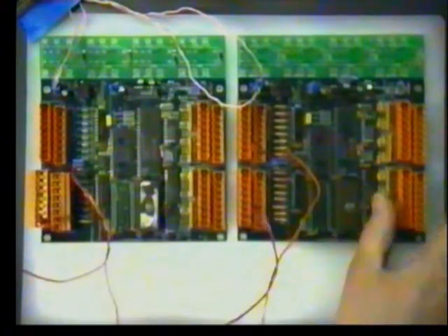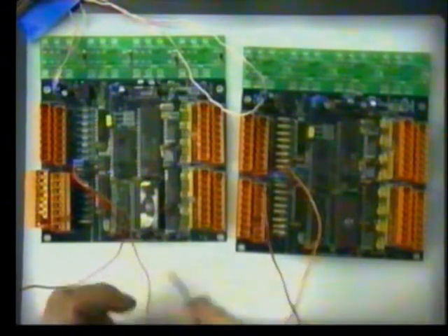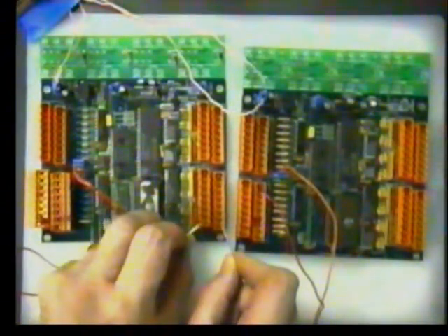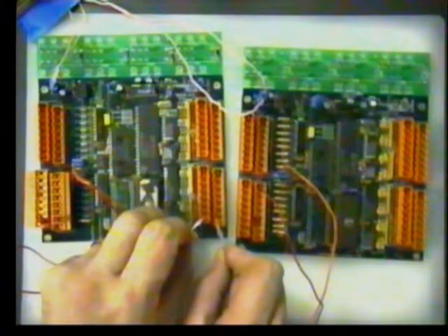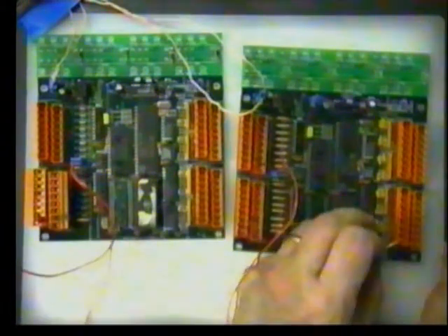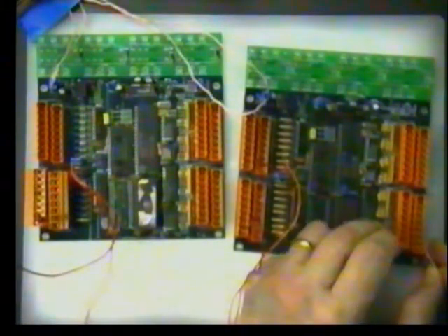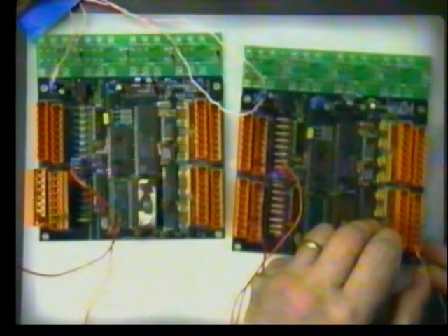So over the CAN bus network, which is just the two-wire connection, we are able to transfer real data between hardwired switches. There's the switches on one card being broadcast on the channel, turning on the actuators. These could be motors, drills, machines, whatever it is at the other end, and that is switching on this unit here. This card, actually, these cards are a family of devices that my company manufactures.